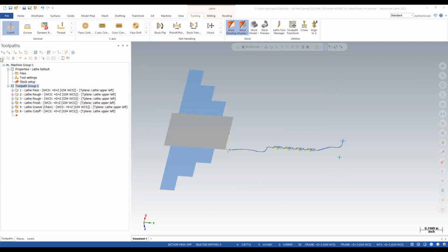So now there are things you've got to erase. Actually, it's only one thing, but I'm going to make you erase a bunch. What does U and W do for a lathe? Incremental. So that should be fine. What's V? V is Y. This post sends the Y-axis home incrementally between every tool change. There's no Y-axis on this lathe.